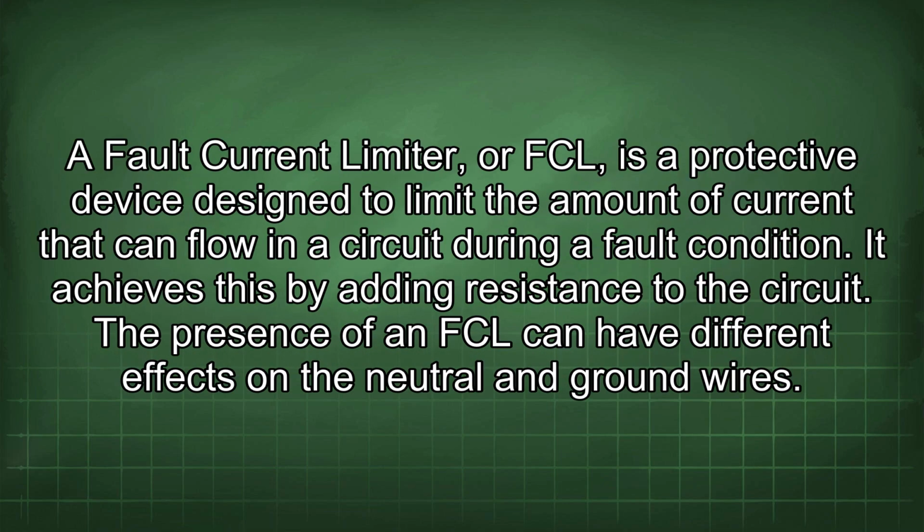A fault current limiter, or FCL, is a protective device designed to limit the amount of current that can flow in a circuit during a fault condition. It achieves this by adding resistance to the circuit. The presence of an FCL can have different effects on the neutral and ground wires.